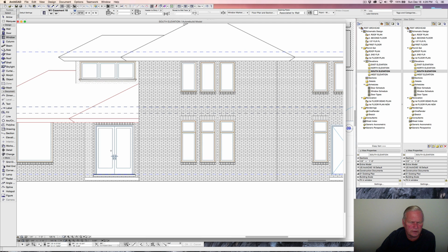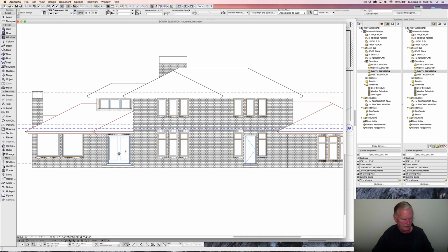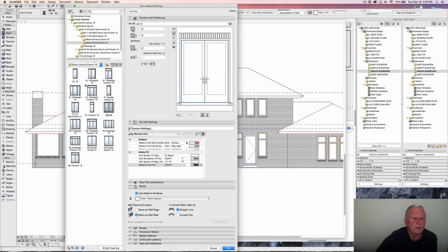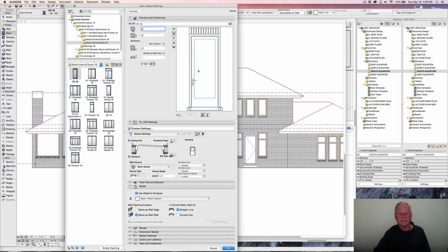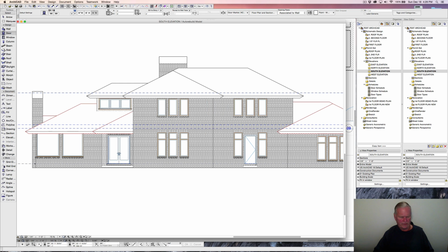and at least we'll be on our way to a door at the front there. Now what we'll do is, again, it's currently in our settings, but we're going to grab it like so. We're going to come up here to single door or doors and go to the single door and inject it. And of course it gives us our size. The only thing we need to change is 3 feet, and say okay. Now that's the setting we have, and we'll put that in that place, and that's then set correctly.